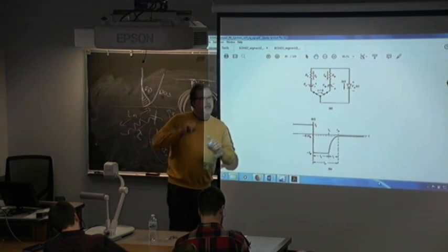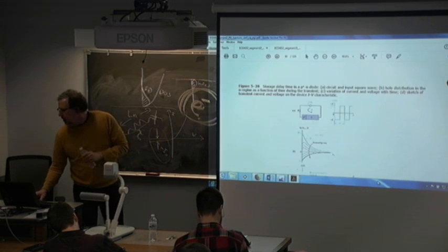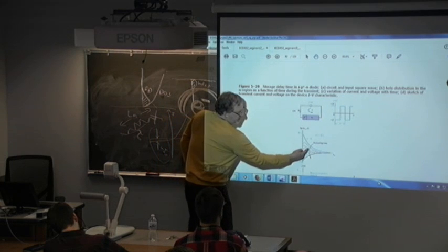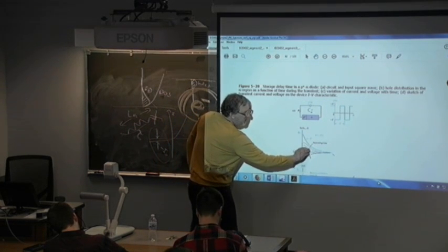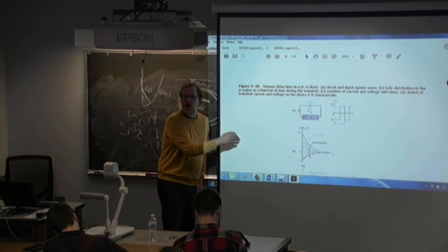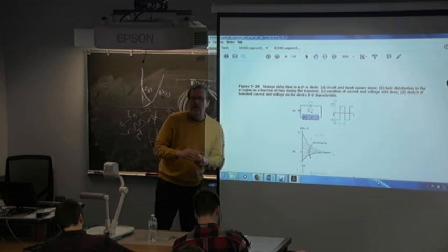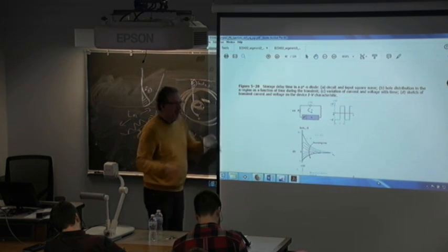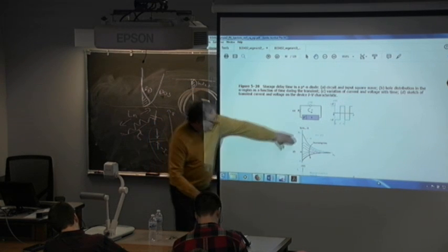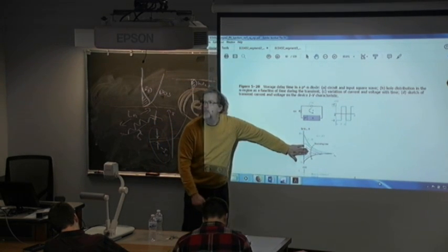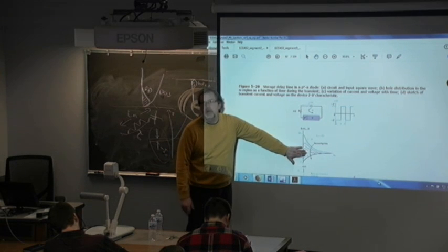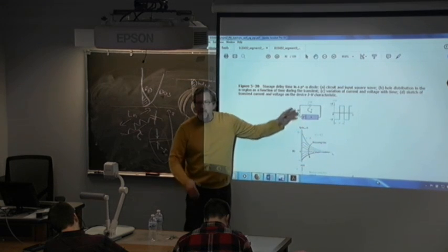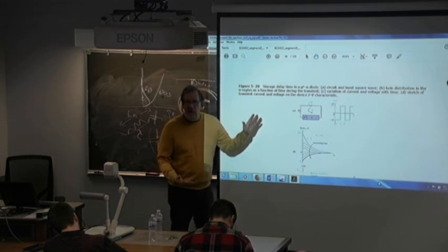Exactly what Stefan said, it's the minority carrier charge. And it's exactly the question from earlier, that it takes so much time for this to recombine, so it's stuck in forward bias. So it cannot stop from being forward bias-like. The junction itself still thinks it's in forward bias, and until this is absorbed by recombination, which is exactly the earlier question, can the junction finally take on the flavor of a reverse bias.